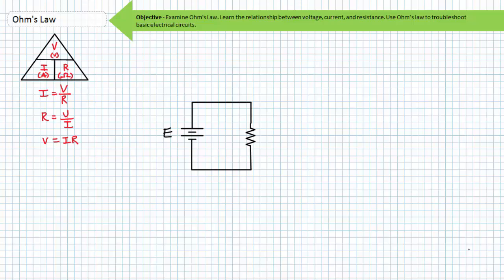A voltage source is obviously a voltage rise, and via the passive sign convention, conventional current leaves the positive terminal of an active source and returns to the negative terminal. If you hook a passive element across a voltage source, what goes up must come down. The polarity markers for a passive element indicate that conventional current enters the positive and leaves the negative. What goes up must come down.